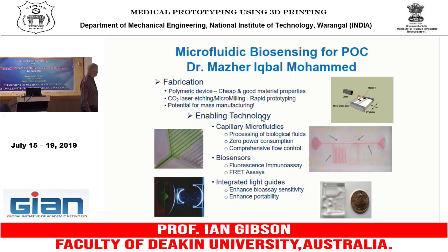Yeah, so there's a lot of things that you need to control in this process. Because really what we're doing here, for example, you put liquid down here, and because of the flow characteristics, the liquid that goes through here takes longer to get to this point than this point. So this is what they call a delay channel. But there's all sorts of different things that you can do. You can see how liquid can be chosen to move in particular directions and not in other directions by changing the dimensions of the tubes. You can inject these in droplet form, so they go in sort of like pulsatile movement, and then mix them, and you can put reagents in at various times.